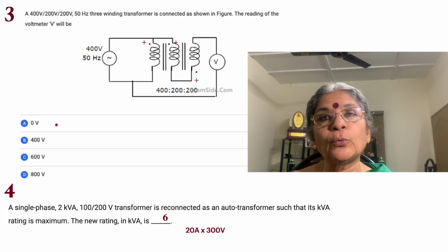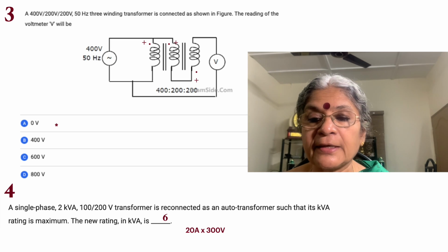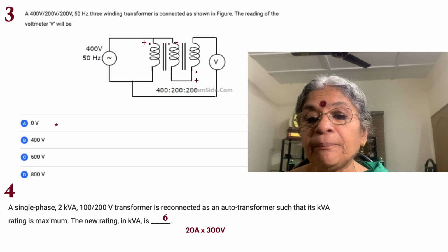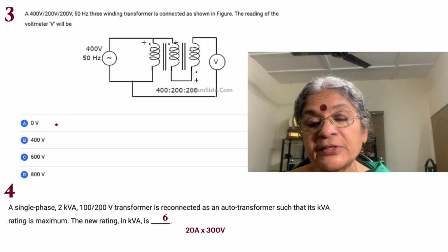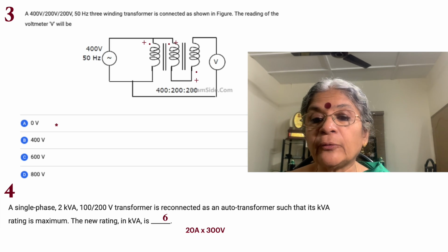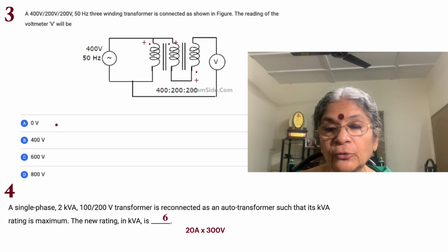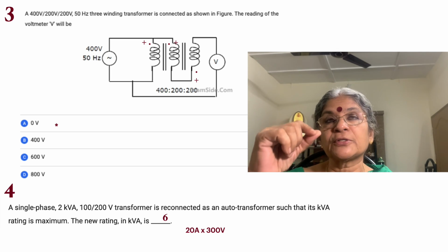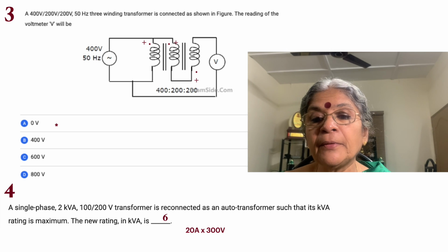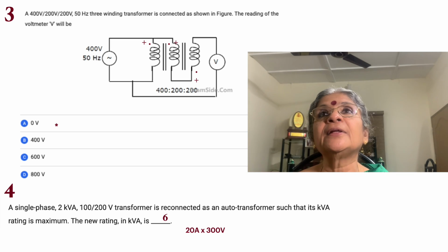Okay, it also induces a voltage in the third winding, such that the dotted terminals are positive in all 3 cases. So we see that we are having a potential rise in the first winding where the voltmeter starts picking up. That's equal to 200 volt. Then we see another potential rise, because it has reached the bottom terminal, and it goes from an undotted to a dotted terminal, or a minus to a positive polarity, in the second winding. And then it comes to the junction between the two coils, and then there is a potential drop.